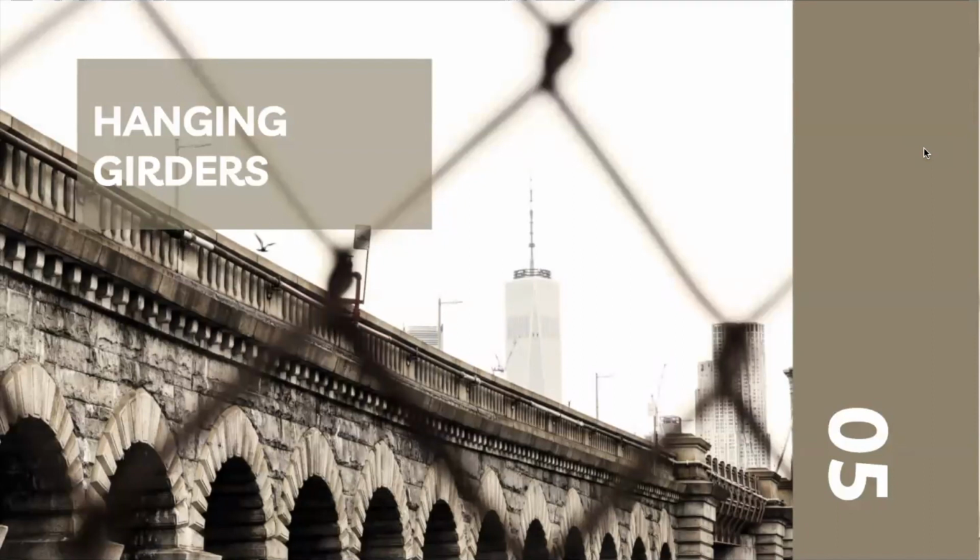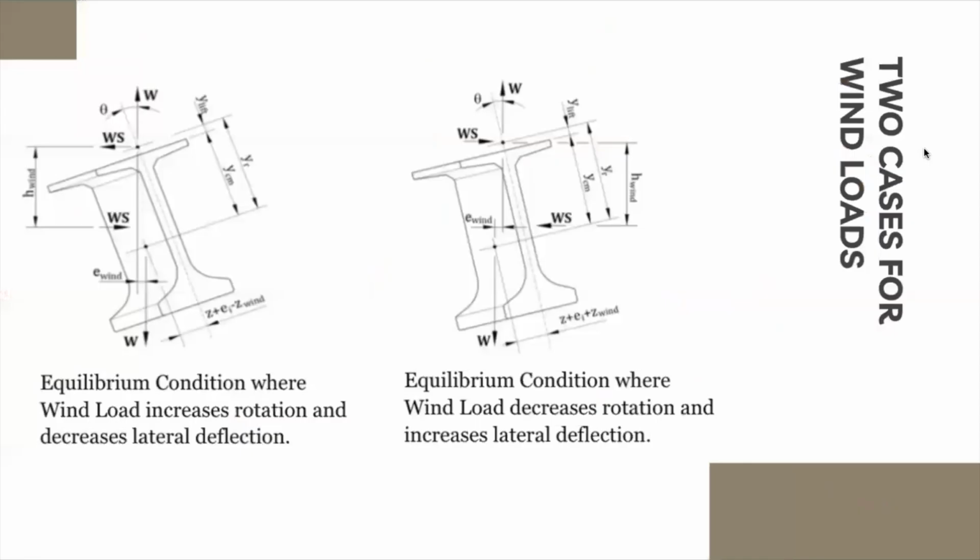Next, we will cover hanging girders. For wind loads, the following two equilibrium conditions must be considered. The left is where the wind load increases rotation and decreases lateral deflection, and the right is where the wind load decreases rotation and increases lateral deflection. From this, we can gather that the rotation and deflection have inverse relationships with similar wind loads.